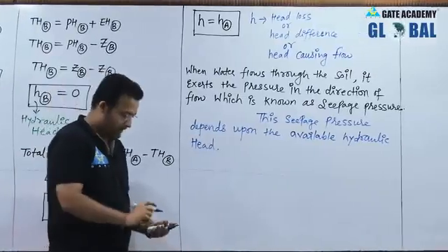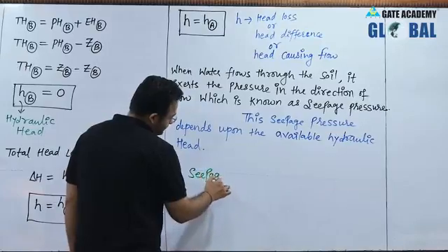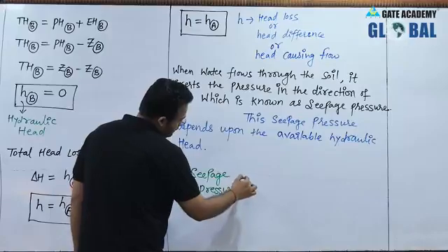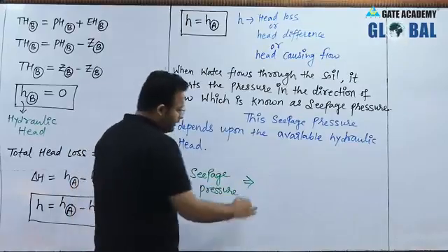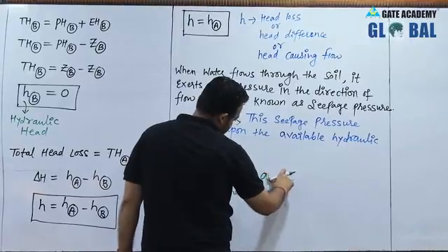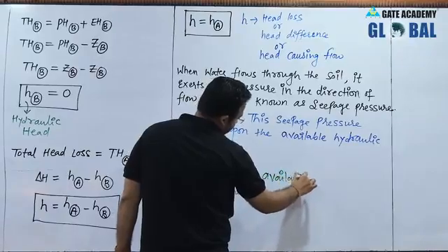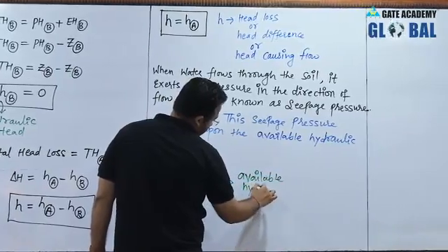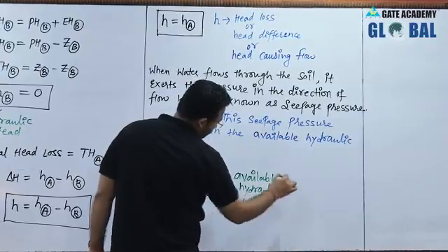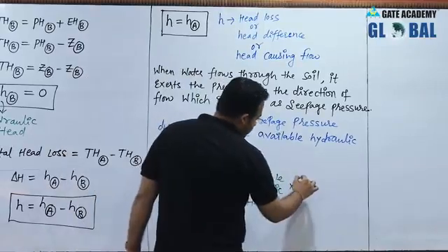Now I can write the formula for the seepage pressure. Seepage pressure is equal to available hydraulic head into unit weight of water.